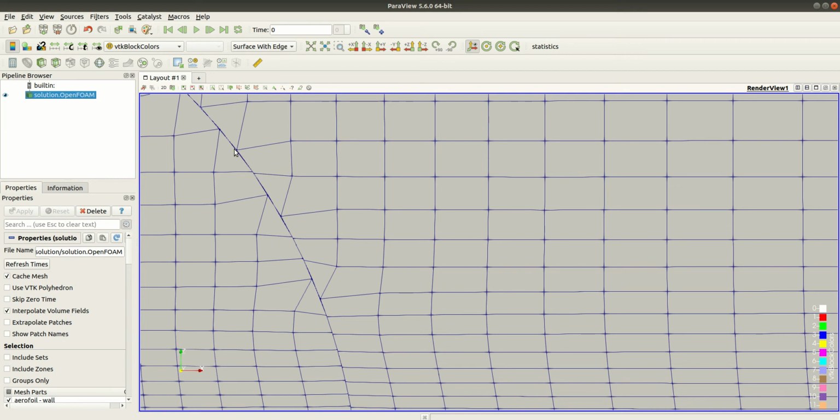While the sliding interface, at each time step, decouples the interface, rotates the mesh, and then recouples the interface so that the mesh is always conformal at the interface, and the flux calculation is done as always throughout all the mesh.